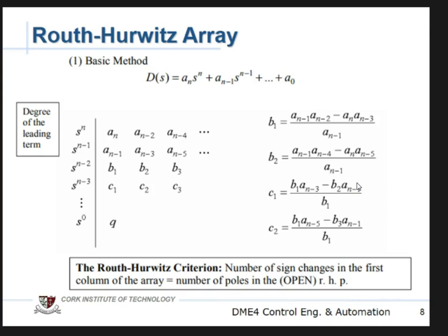If we want to figure out the gain that makes it unstable, we look down this column and figure out when one of these coefficients becomes 0, because then I'm looking at the sign change. It goes from positive to 0, for example, and the next one would be negative. Once we find where one of those first column entries becomes 0, that gives me the ultimate gain. To construct the elements, we're looking at the denominator: s cubed plus 3s squared plus 3s plus 1 plus Ku.